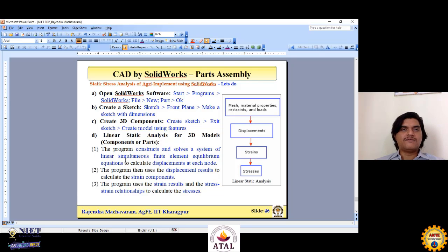For example, in a robotic arm, the fingers are actuated. Once they are holding the load, they are resting onto the base. Wherever each link is connected to the base, there we have to give the boundary conditions. Now the fingers are actuated and holding the load of the object. There we have to calculate how much force is required to hold a particular object. That force we give as an initial condition.